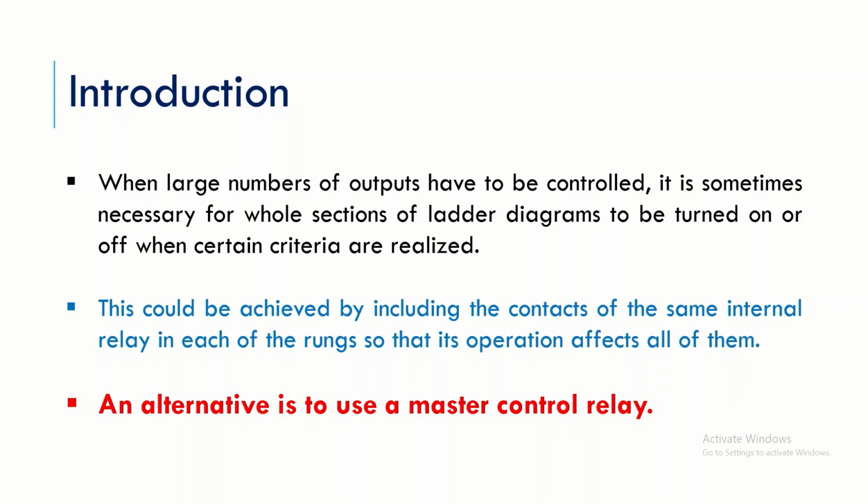Now, if this has to be done, then we can think of one immediate solution. We can use one internal relay for each and every line, and the contacts of that relay can be used in each rung of that line.